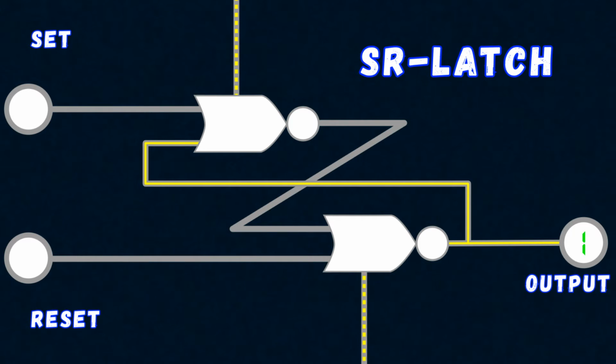All right, now let's try to rewrite our cell. That is, change the value stored in it from 1 to 0. To do this, we need to send a signal to the reset input and see what happens in this case. The signal applied will reach one of the inputs of the second OR NOT element, and since now one of its incoming signals will be equal to 1, the outgoing signal will become 0.